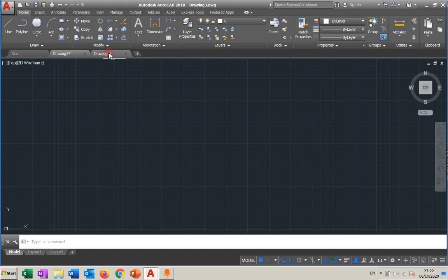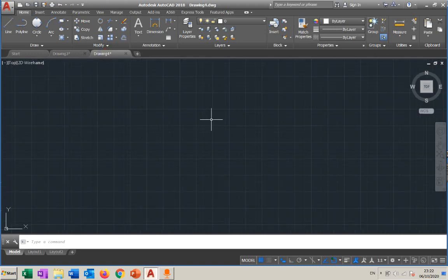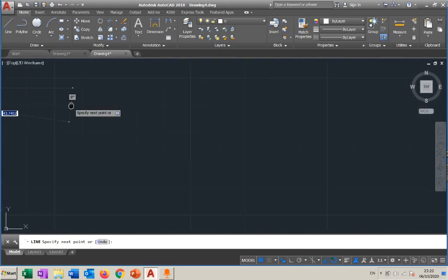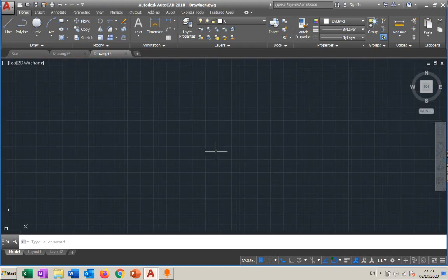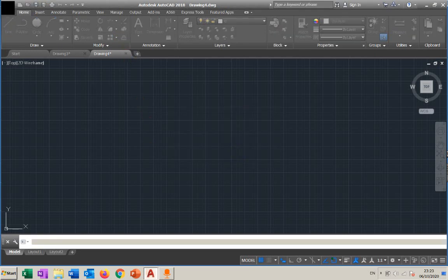So why would I do this? I will open a new sheet, change the unit to inches, and then draw it as inches inside here. If I draw something inside here, this is inch, 300 inches. Why? Because each unit basically means 1 inch. Now, for example, this is 25 inches. This is what we have to do. So now you know that multiple sheets are required if you have drawings with different unit styles. If all of them have the same units, you can draw all of them in one drawing.